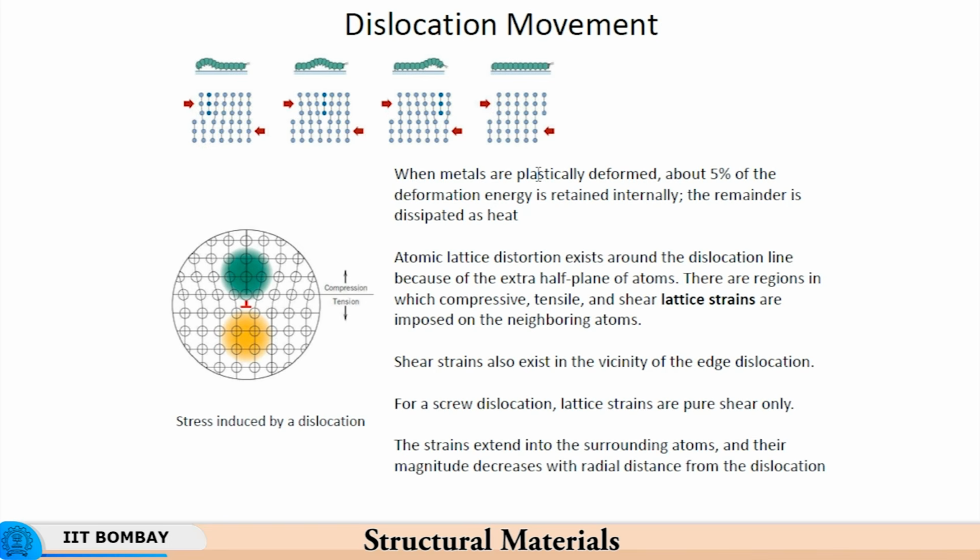lower stress, right. So now you have dislocations moving at a certain threshold stress which is called the yield stress of the material. So there is a transition from elastic to plastic regime, and so the yield point is essentially the stress at which the dislocations just start moving.